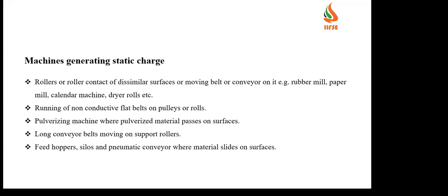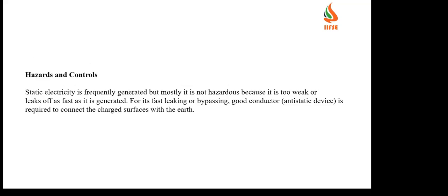So there also, there will be a chance of generation of static electricity. And feed hoppers, silos, and also pneumatic conveyors, where the material slides on the surface. So feed hoppers, where we charge the material, the sliding there means friction, contact and separation activity happens between the materials. In that case also, there will be a chance of generation of this static electricity.